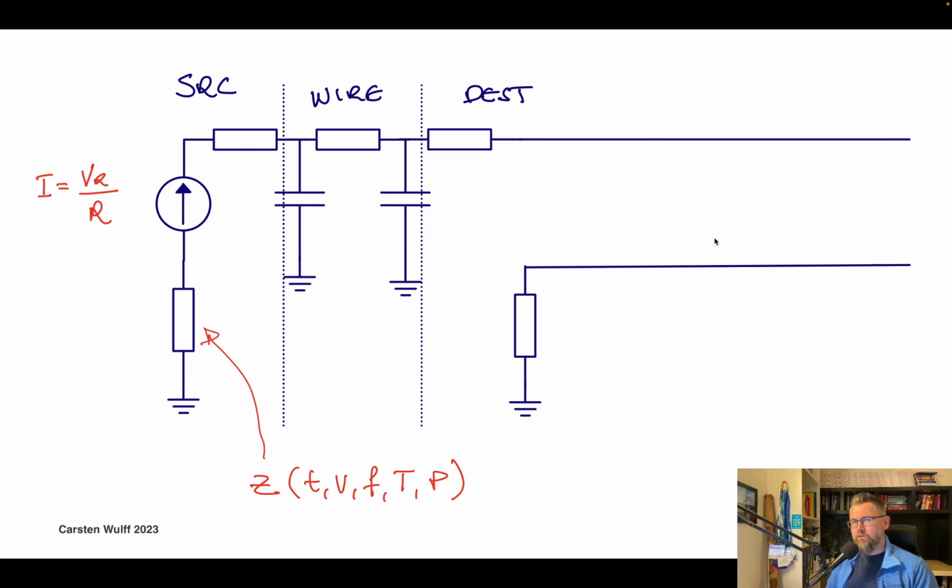It is also a bit simpler to copy current than it is to copy a voltage. When you copy a voltage, you can hook up all the destinations to the same voltage, but imagine what happens if one of the circuits is badly designed or maybe hasn't thought about everything, and it kicks back noise onto the voltage line. That will then distribute to all the different destinations. Now you can of course insert buffers like a unity gain amplifier, but that adds offset, so it goes into your error budget for this reference voltage.